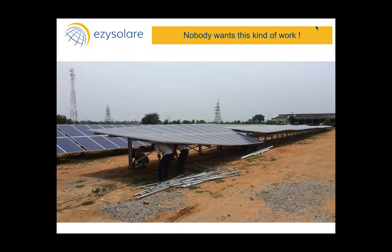I went to one of the plants a few days back and clicked this photograph, and it really scared me off. I hope all of you can see the photograph. This is a seasonal tilt structure at one of the plants, and when the seasonal tilt is going on, you can see what kind of bending is happening on the structure. I am told that this creates micro cracks in the structure, and it is expected that in the next couple of years, with this kind of bending happening twice a year, the modules will get severely affected.